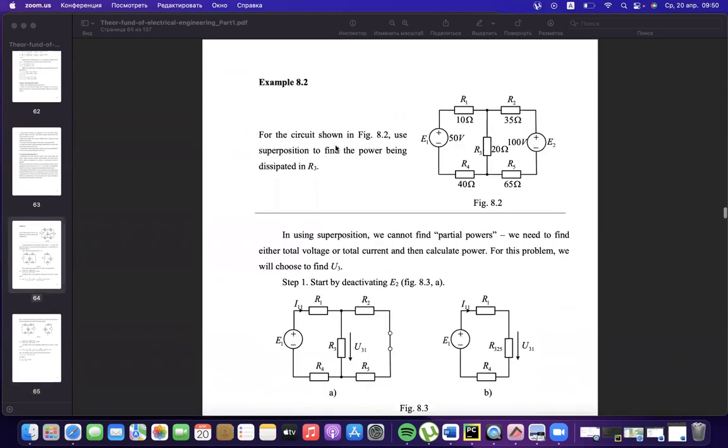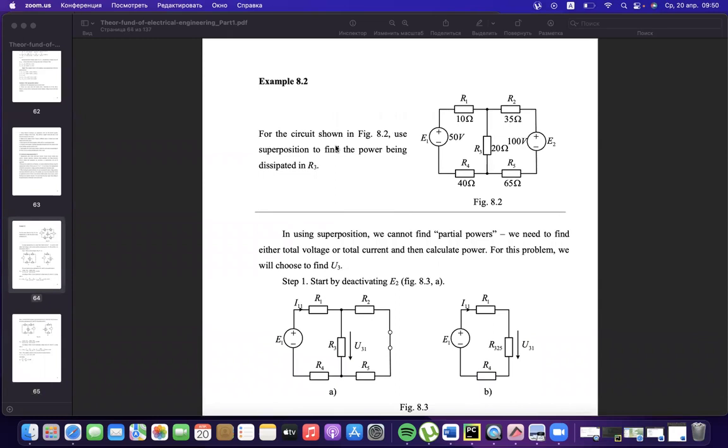It is just a second example, the same idea for the superposition method. And you could use it on any circuit if your resistors are given by numbers, by constants, for linear circuits, and independently of the kind of energy sources. The energy sources also could be mixed, not only direct current, it could be some combination, for example, of direct current and sinusoidal current sources. Just like that.